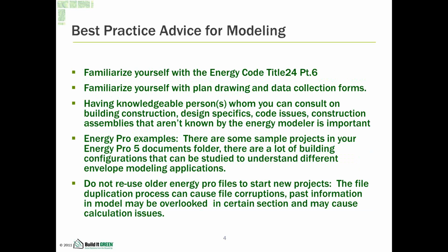Okay, so some best practices for modeling, just some advice that helps me work more consistently, and some advice I give to colleagues that has helped them. You want to familiarize yourself with the Energy Code, Title 24, Part 6. Familiarize yourself with plan drawings and data collection forms. You should understand how to look at plans or drawings and how to read data collection forms.